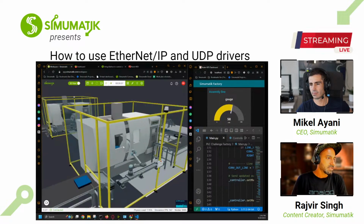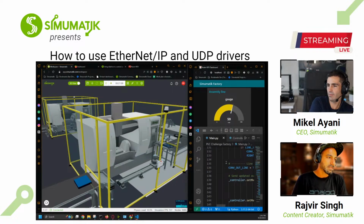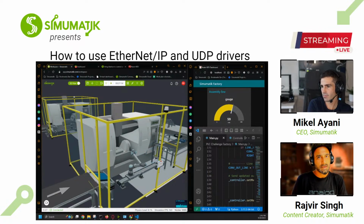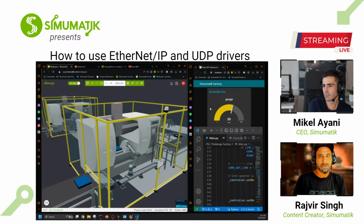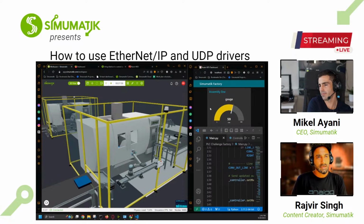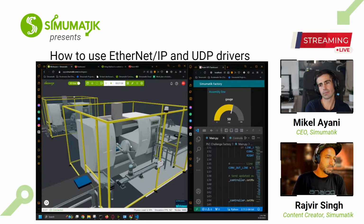Now, if you notice, the number of parts that are being produced, these are going to my dashboard. And my dashboard is running on Node-RED. So what is happening? The Python is taking the signals from the Simumatik, counting the number of workpieces that are completed, and sending to the topic, which we define in the Python, the number of parts completed. And then in Node-RED, we are subscribing to this topic to get the data. So the information flow is from Simumatik to Python, from Python to broker, from broker to Node-RED.